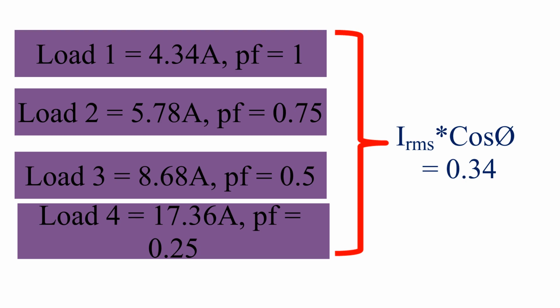So let me conclude that inverters are rated in kVA, not in kilowatt, because if the ratings are given in kilowatt, we may wrongly connect the load without knowing the power factor and the current, and that will result in the failure of the inverter.